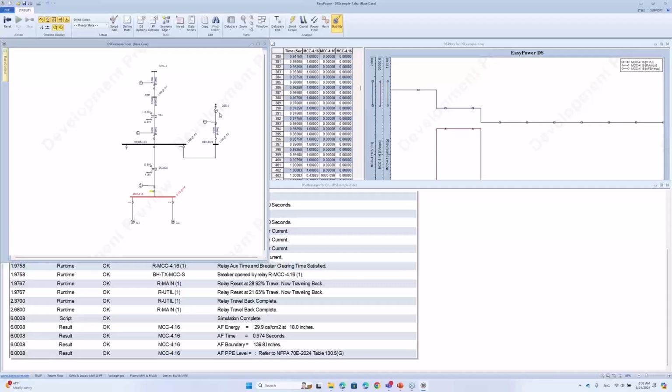If you have a static excitation system, the fault current may be very consistent with your short circuit result. If you have a DC excitation system, which is very slow, then you may have a much smaller fault current. Eventually, you will have much longer fault clearing time, which may lead to a much larger arc flash energy, right? Because of the relay settings.